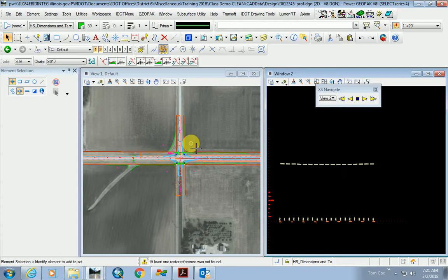The overlay profiles are handled a little bit differently than one where you're defining the geometrics of a profile. All we're really going to be doing is taking that existing profile and essentially copying it parallel, so to speak, or storing it within coordinate geometry at an offset elevation above the existing. So the way that you do that is in coordinate geometry.